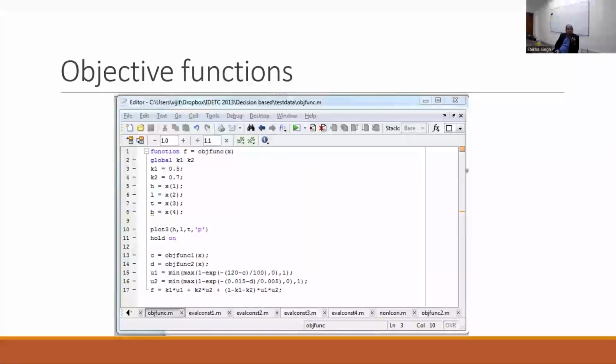K1 and K2 you will assess like we discussed last time. So basically that measures your relative inclination. Somebody will say, yeah, just give me something cheap, I don't care too much about deflection. Somebody else might say, no, I want a sturdy beam, even if it's more expensive. So people's different preferences could be represented in this fashion. The single attribute utility functions are exponential, as you can see. And we solve this optimization problem. Now we have done an overarching optimization using our knowledge of multi-objective optimization and our knowledge of decision making to optimize the system.